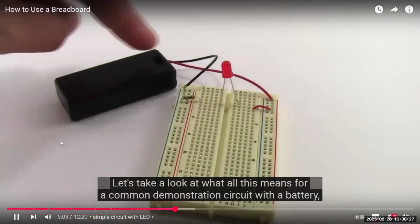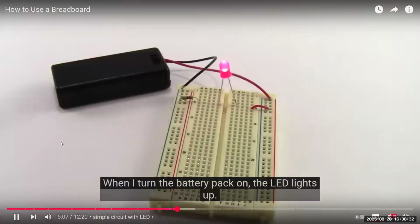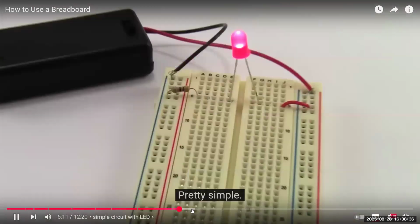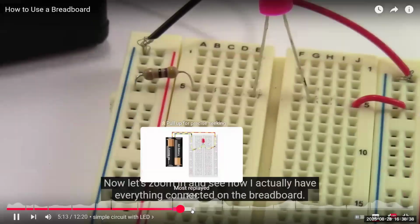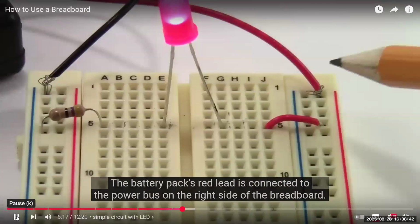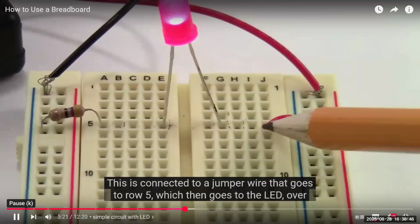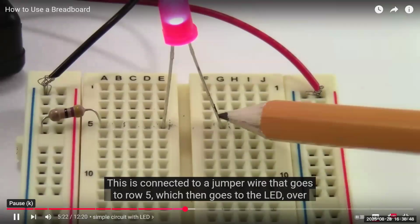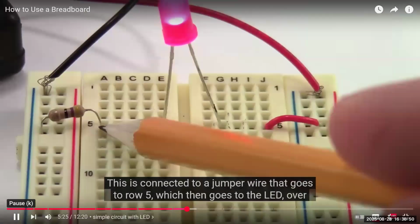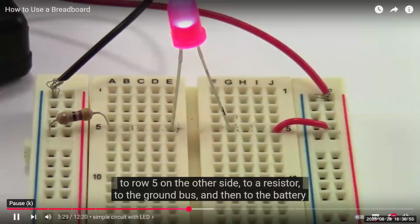Demonstration circuit with a battery, a resistor, and an LED. When I turn the battery pack on, the LED lights up. Pretty simple. Now let's zoom in and see how I actually have everything connected on the breadboard. The battery pack's red lead is connected to the power bus on the right side of the breadboard. This is connected to a jumper wire that goes to row 5, which then goes to the LED, over to row 5 on the other side, to a resistor, and you can see the circuit is complete through the battery.